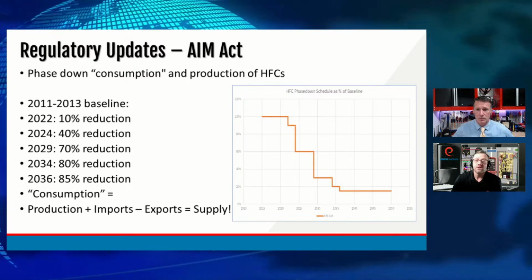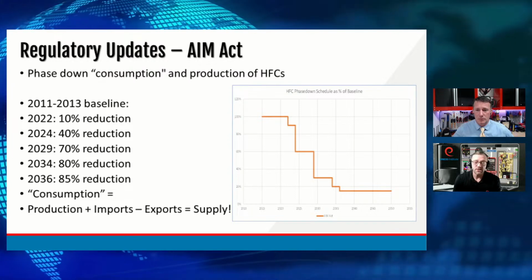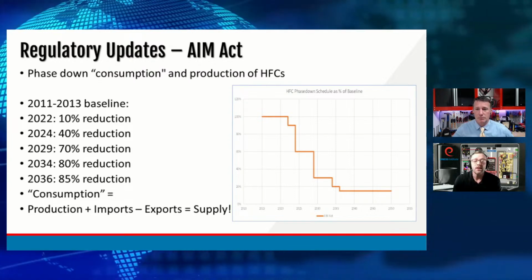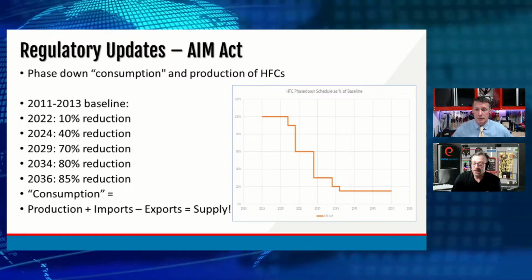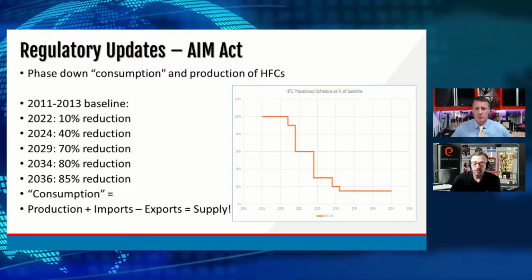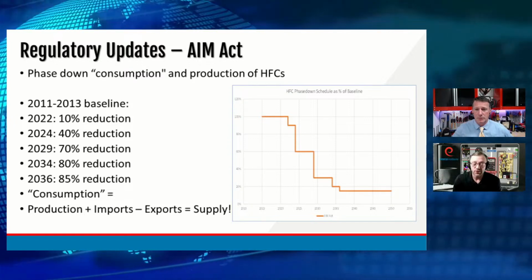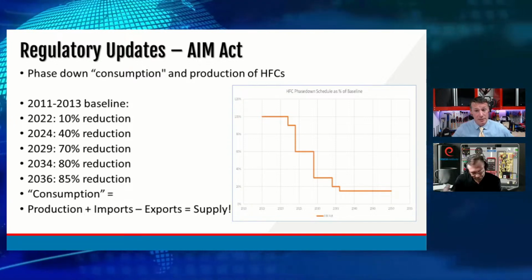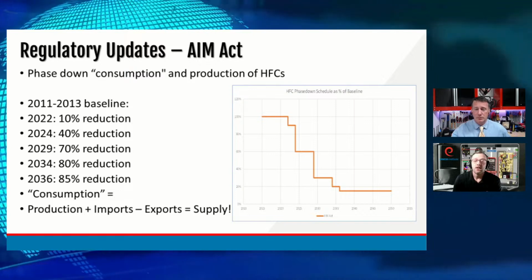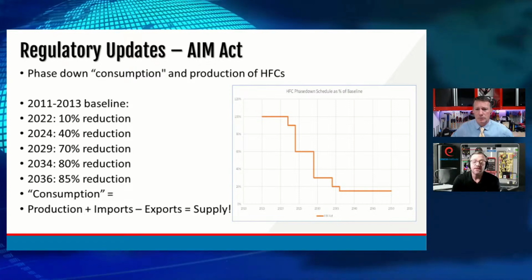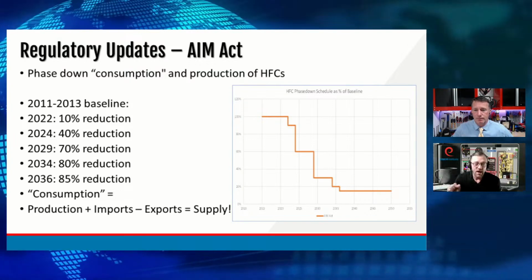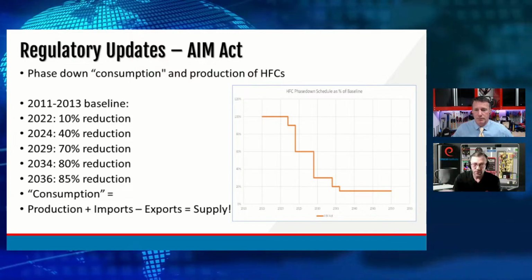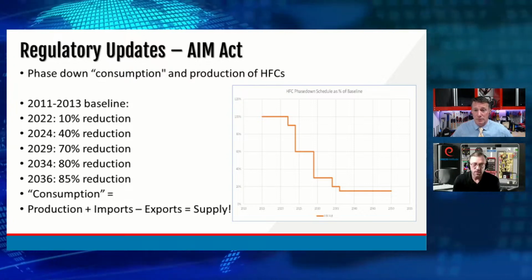So when you ask what's going to happen to, say, 407C, well, it does have a pretty high GWP. Some people will still make it, but we'll see it reduced, again because of its high GWP. We're going to see the higher GWP refrigerants affected the most, and the soonest. It's based on credits or allotments that the EPA hands out to the manufacturers, and each tank pulls from that allotment. Once they've reached their limit, they're done for the year on the carbon emissions.